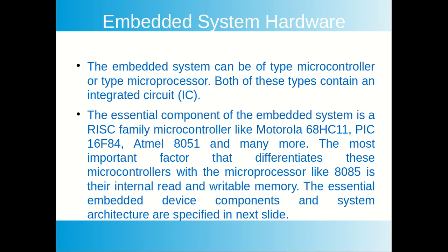Embedded system, in either case, an integrated circuit is at the heart of the product that is generally designed to carry out computation for real-time operations. Microprocessors are visually indistinguishable from microcontrollers, but while the microprocessor only implements a central processing unit and thus requires the addition of other components such as memory chips, microcontrollers are designed as self-contained systems.